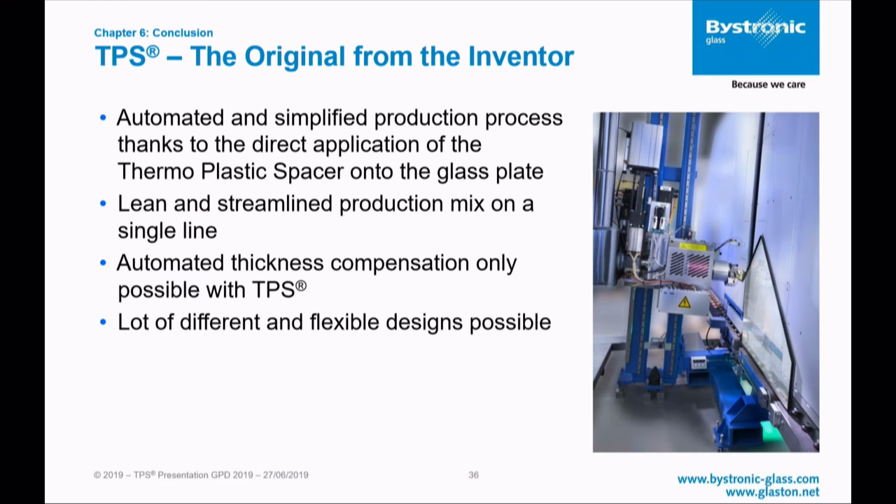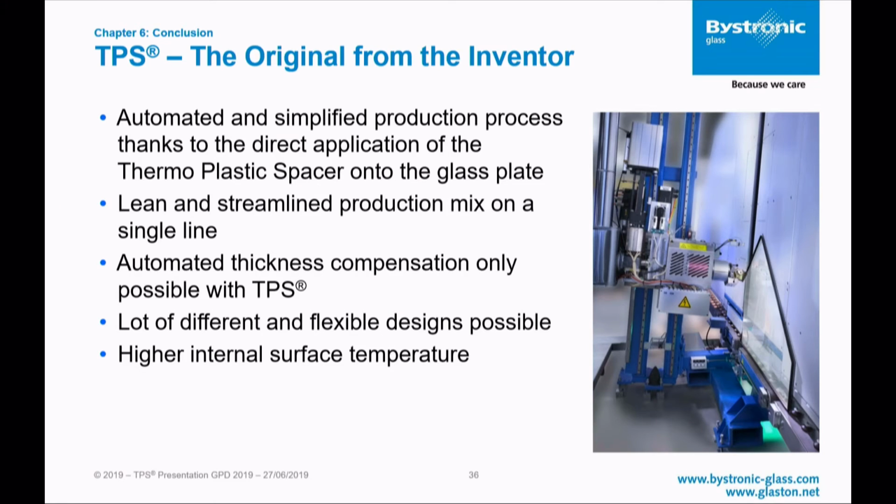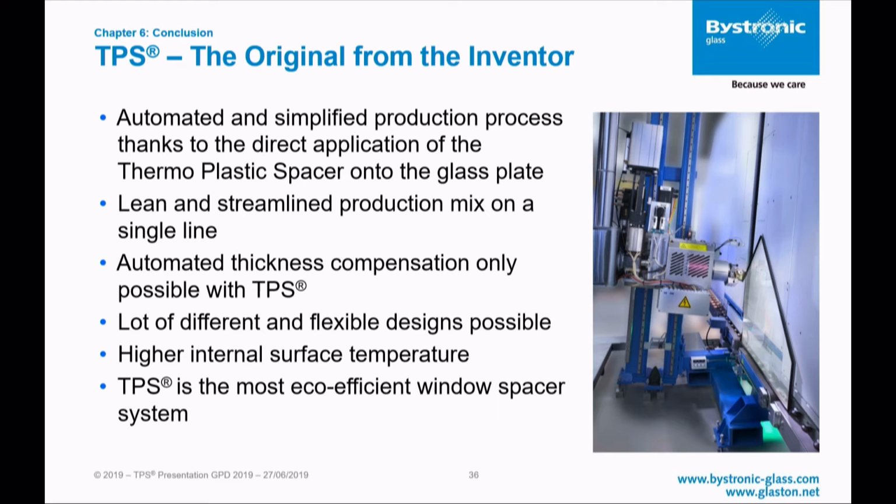It's very flexible to change over without any downtime, and the surface temperature is also higher in comparison to other systems, with lower condensation at the glass edge. Based on the studies, you see that the TPS is the most efficient spacer system that you can get on the market.